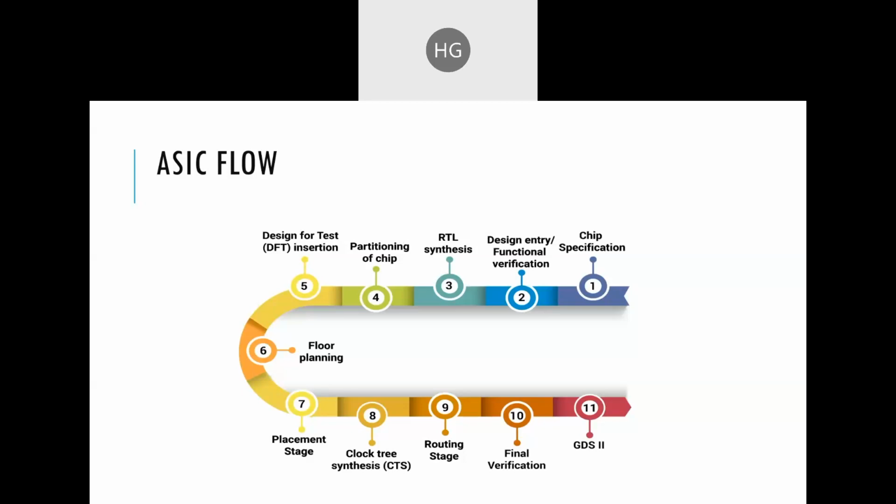Okay, okay. So basically, RTL synthesis is the process in which we convert the design into the netlist. A netlist is basically a formation of the circuit, with all the details, so the design becomes a real circuit. Before synthesis, you can see the design in code form, with code for every component, maybe a mux, a sequential circuit or a combinational circuit. After synthesis, you can see that design as a circuit.